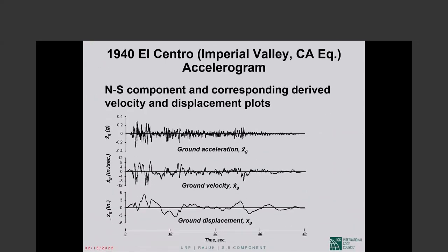Now, the response spectrum is directly related to the design ground motion at a site. Design ground motion not at the source of the earthquake or somewhere else, but at the site on which we are going to build our structure, the structure that we are designing.